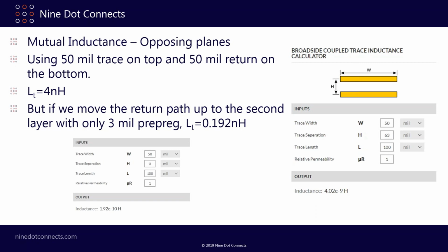That's also when you start doing complicated board stack ups, just a side note, and you're trying to provide power to high current devices like an FPGA, you're going to want to have power and ground very tightly coupled in your board stack up and close in layer count to your load, just for this reason. This is part of the reason, I should say.